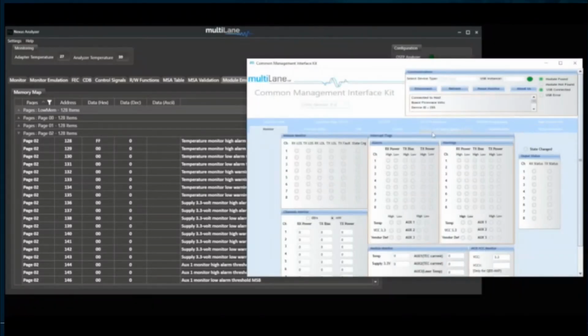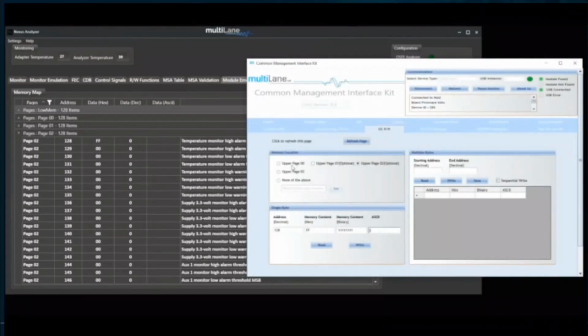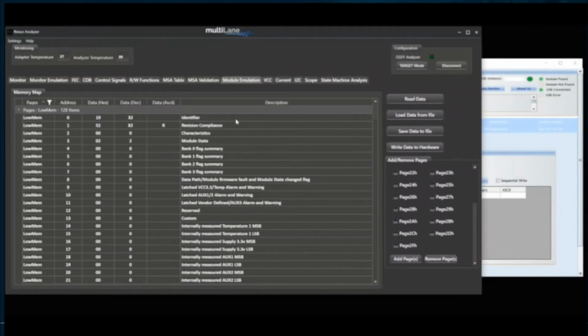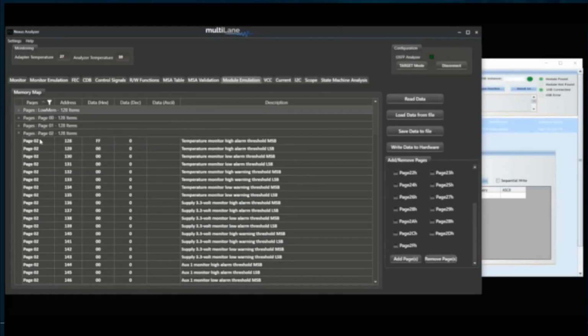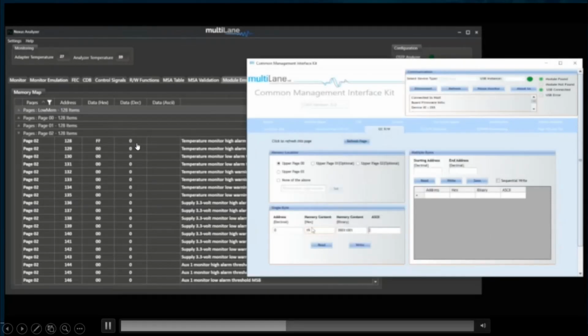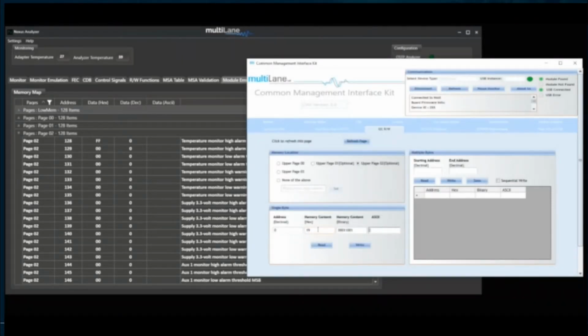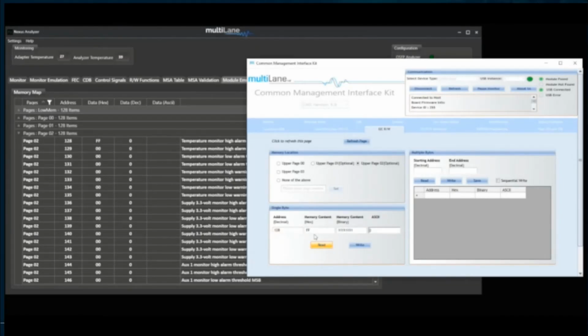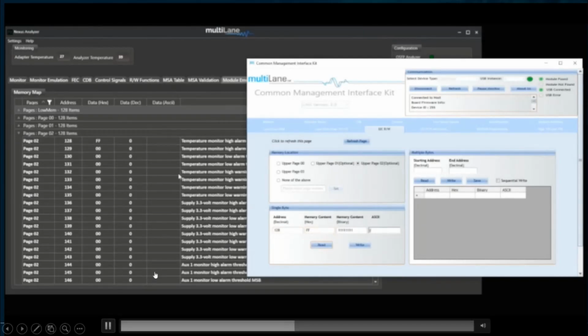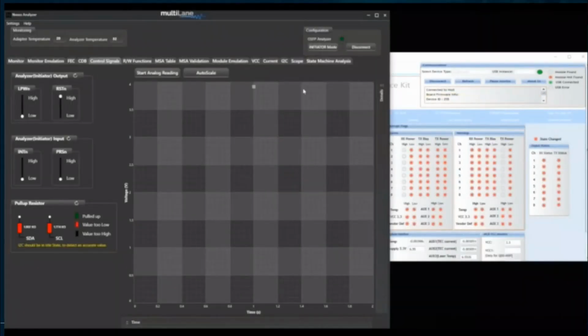So I go to my host UI, I access the I2C read-write tab, and I start by reading register 0 from low memory, excuse me. And I should expect 19. There we go. And then I do the same exercise for register 128 of page 02, and I effectively read FF. I will wait until you guys can see that as well. So there we go. With this very simple step, I eliminated that any issue is coming from my host.